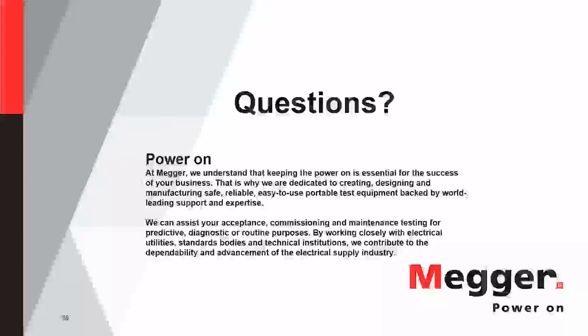Whereas an analog transducer, what you're doing is you're applying a voltage across the resistor. So now, if I'm using an analog transducer and I have a 500 millimeter transducer and I'm trying to measure a stroke of 10 millimeters, I really don't have a lot of resolution. Whereas the digital one, it'll be the same resolution across that.